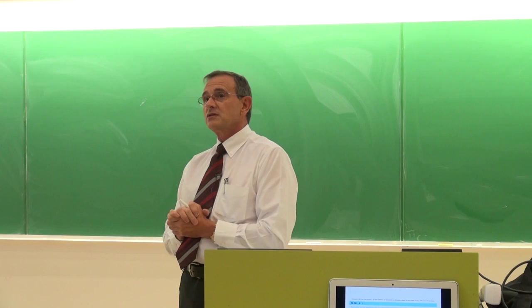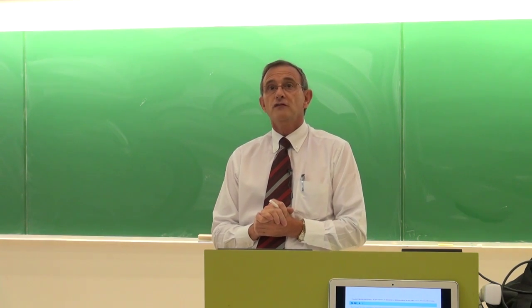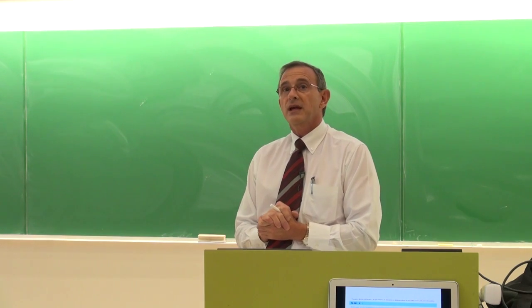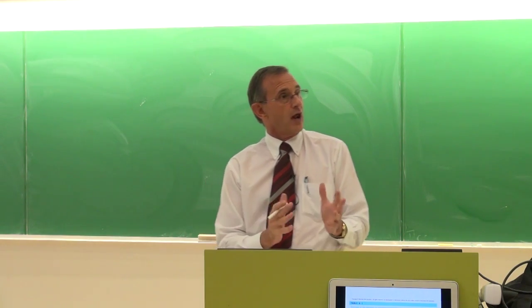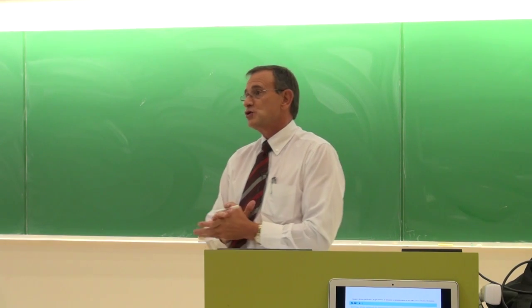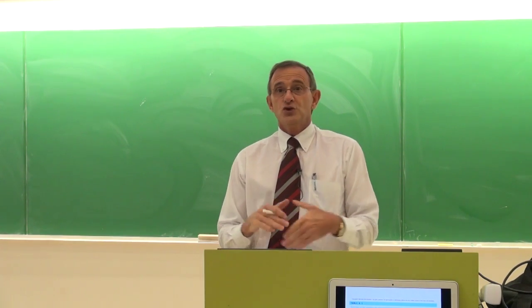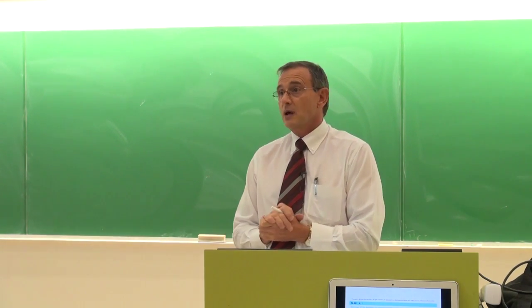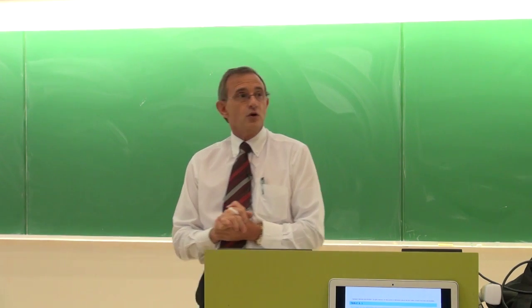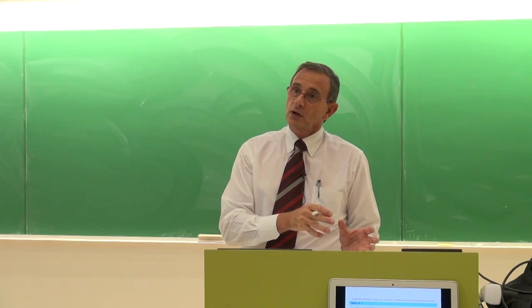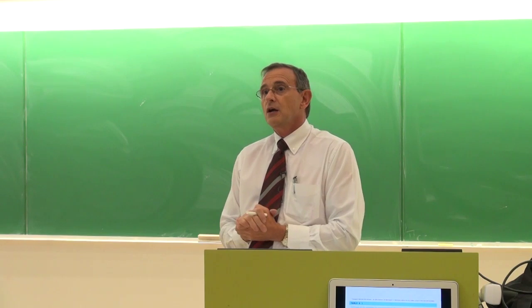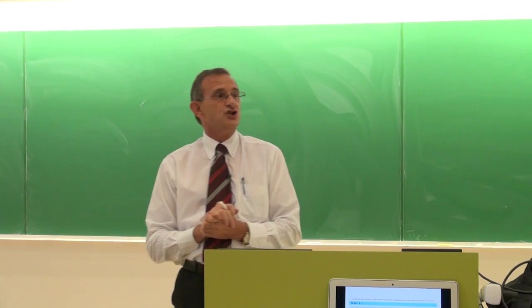Then from first principles we have derived a solution for the so-called lumped system. It's a very easy solution, however it has limitations. In many cases, we can use the Biot number to help us to make decisions if we can use the lumped system or not. Unfortunately, many applications we cannot do with a lumped system approach. So in this textbook, we've started with the most simple and then we make it more complicated. So the next stage in increasing the complexity would be to look at more simple geometries.